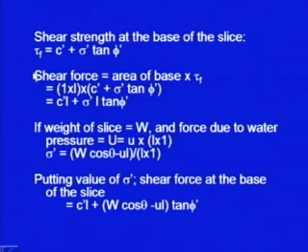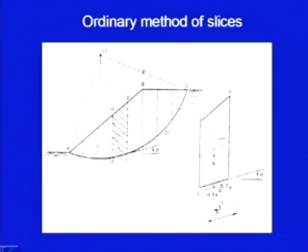So, this is the maximum shear force which can develop. So, area of the base is equal to 1 into L. L is this dimension. In fact, this will be roughly equal to this small arc. So, theoretically it should be taken as that arc, but roughly you can take this chord DC.